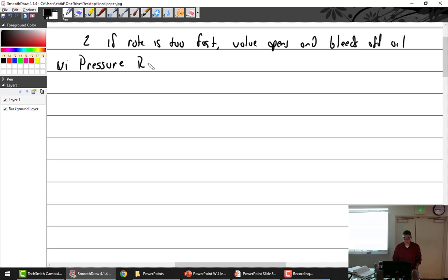Pressure ratio controller. That was the one that was connected to ambient. Ambient and upper deck. At higher altitudes, turbo must work extra hard to keep manifold pressure set for max horsepower.